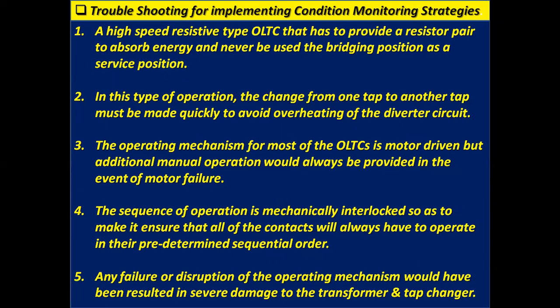Number 3, the operating mechanism for most of the on-load tap changers is motor driven, but additional manual operation would always be provided in the event of motor failure.